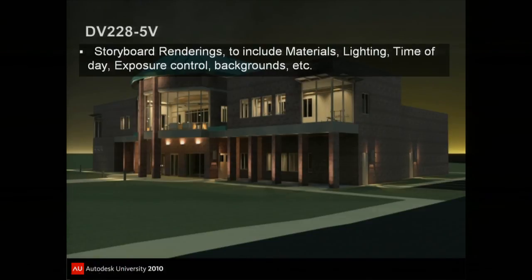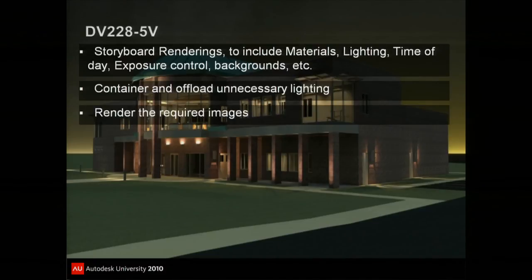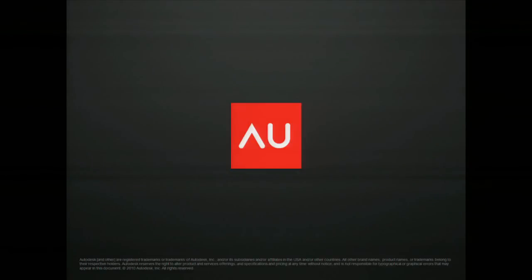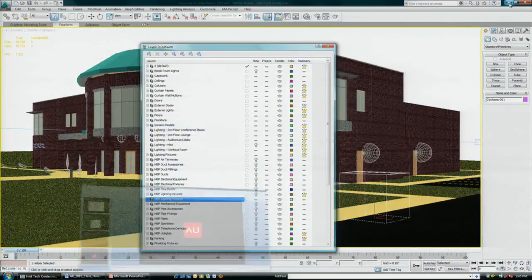So the thing to do here is you want to storyboard your renderings to include the materials, the lighting, the time of day, the exposure, the backgrounds, and everything else. Then you're going to container off all the unnecessary lighting and, by the way, geometry as well, just like we just talked about with the structural model. If you don't see it and it's not contributing, it can go away. You can container it off. Then you're going to render your required images. And that gets you through that part of the PowerPoint of what the workflow is.